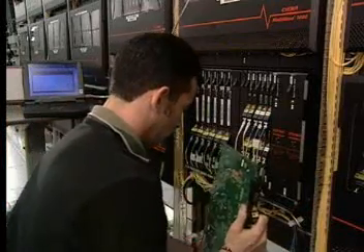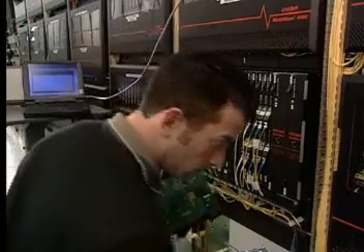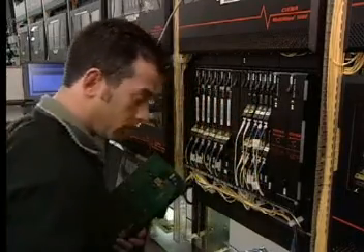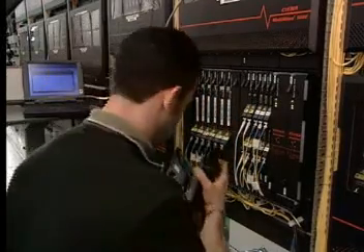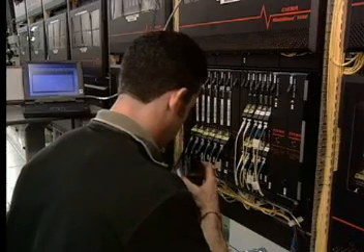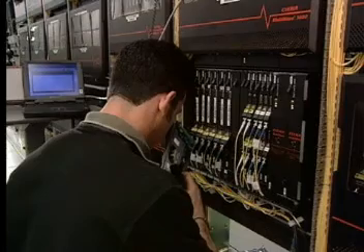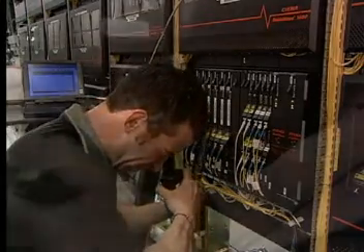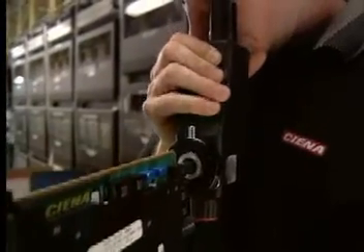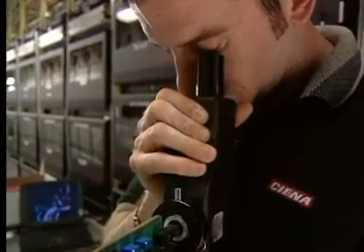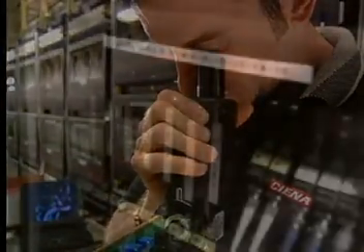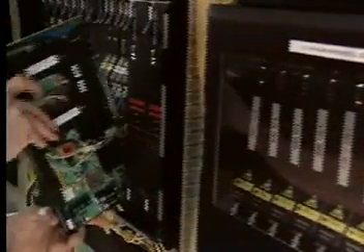All connectors in the fiber system should be checked with the inspection scope prior to mating. This includes the connectors on circuit cards as well. Even when installing a new circuit card or piece of fiber optic equipment, never assume that because the product is new, the connectors will be clean and free of damage or defects. In fact, new connectors are often too dirty to put into operation because of residue from the manufacturing process or